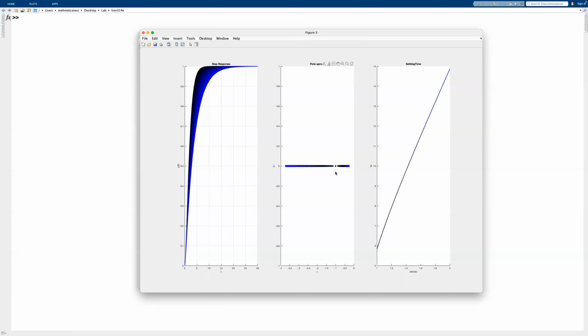Why would I bother with a system that looks like this to design a certain system? Because in the future, we will see that this high rate of change here is also nothing that we want in control system design. So this is not an ideal system. We don't have a settling time formula exactly for this, or not quite that handy, like 4 divided by zeta times omega n. So that doesn't work. We don't have any overshoot. Therefore, we don't really use this for design purposes.